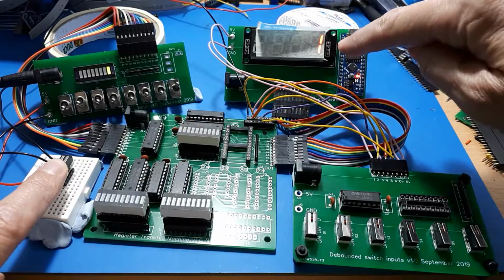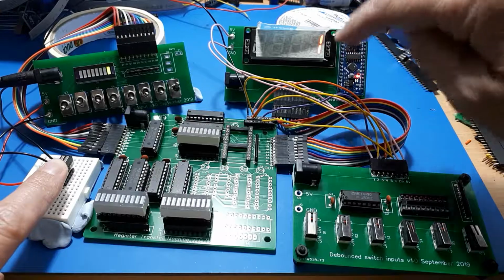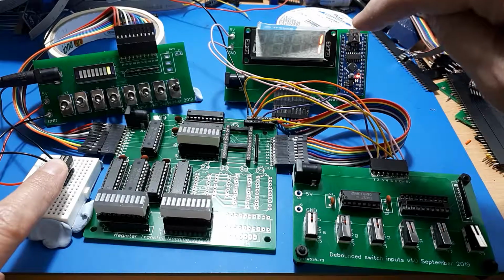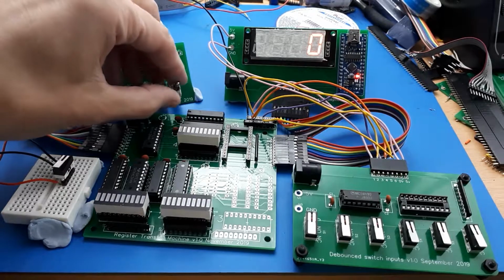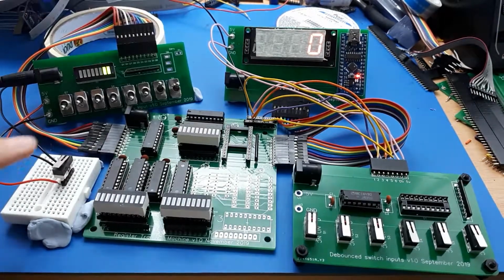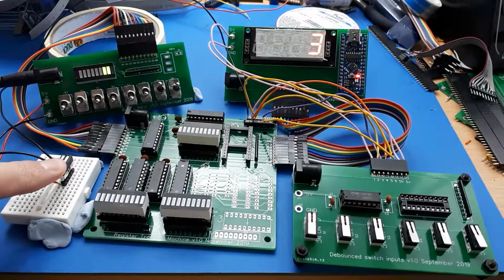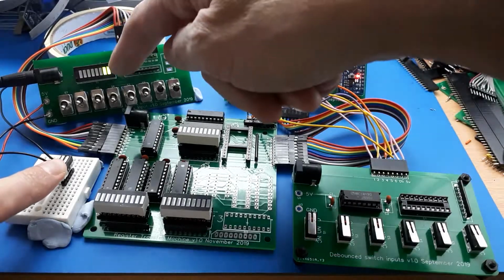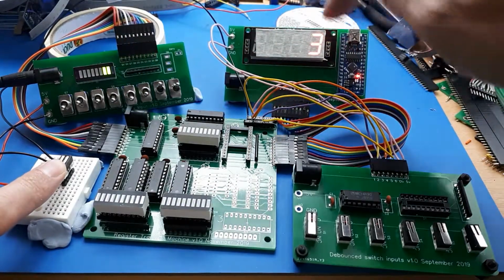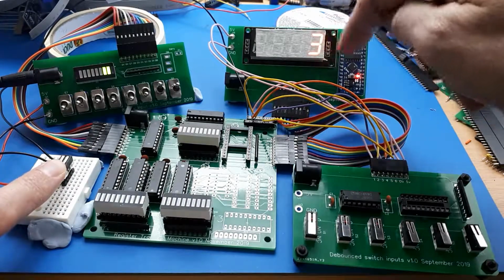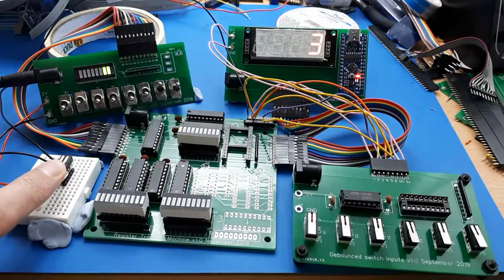I've got a lot of light shining on there. It's hard to read. I'm going to try and improve on that. Okay, so if I publish 1, we have a 1 on the screen. If I turn 2 switches on and publish again, we've got 3. So I'm publishing from the input device straight through the CPU and out to the output device, because the output device is always displaying what's on the bus. So that's just a way of seeing what's on the bus.